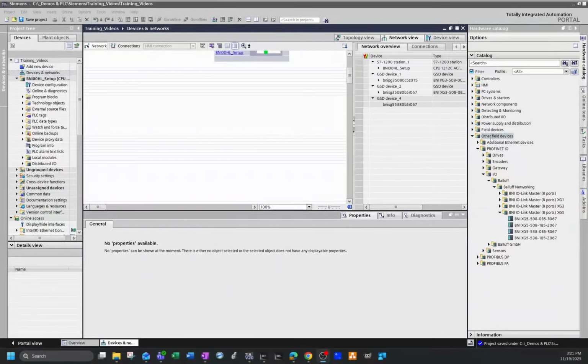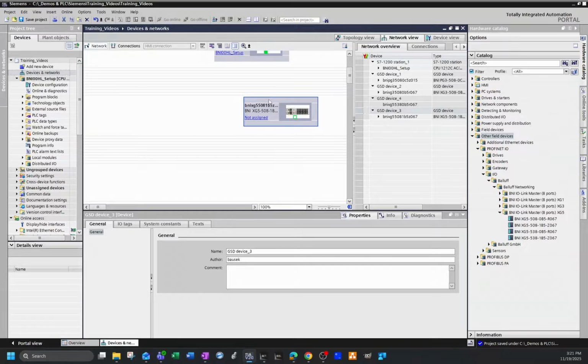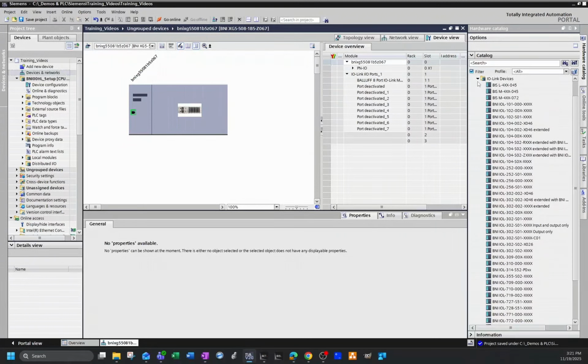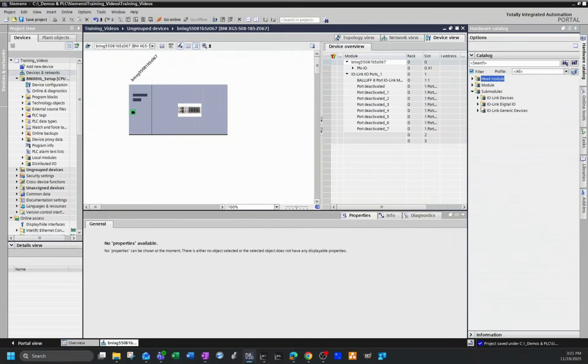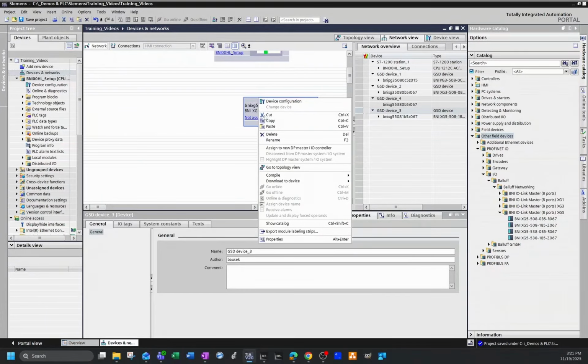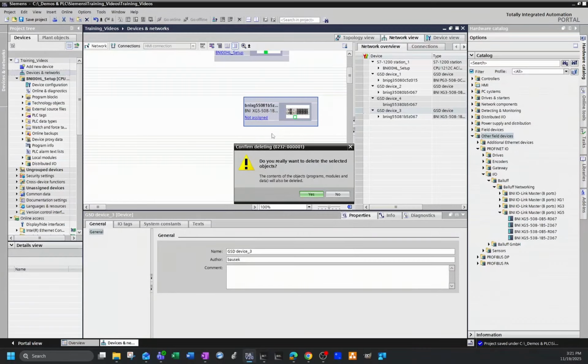Let's begin by referencing the typical GSDML file, which can be accessed at balluff.com and is available for download under the BNI00K6 software section. The GSDML file is already being utilized to import Balluff IO-Link products into your project. For added convenience, the latest Balluff Engineering Tool installation introduces a new custom GSDML feature, enabling users to seamlessly integrate custom products into their hardware catalog.